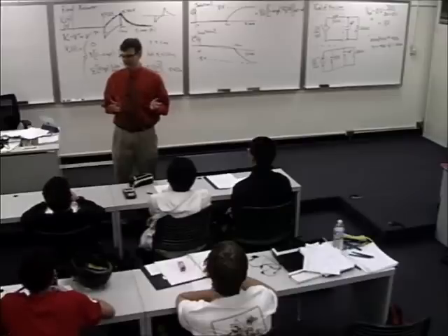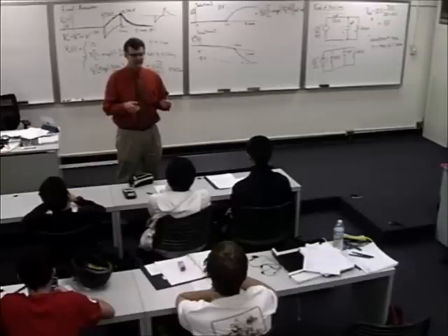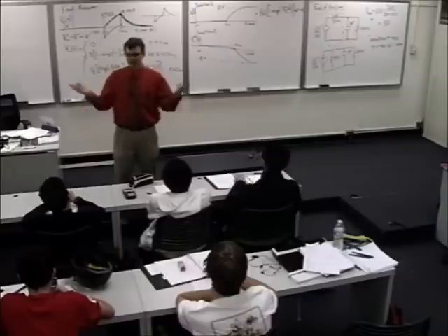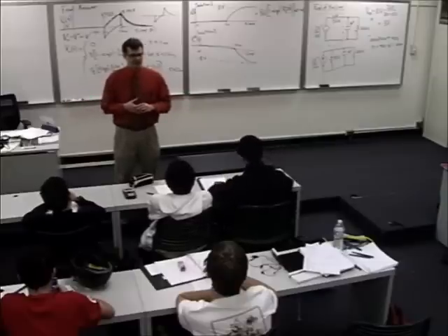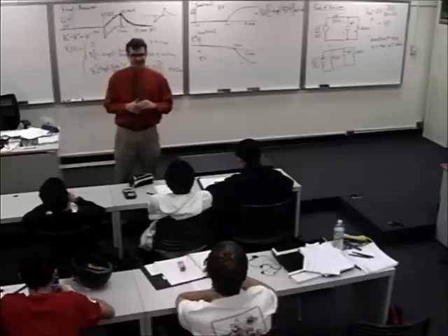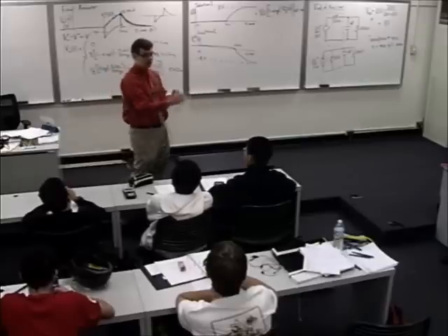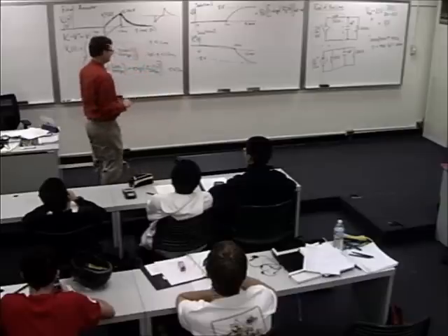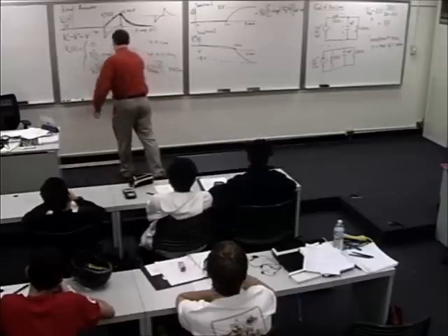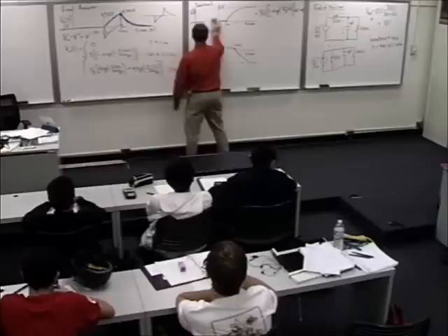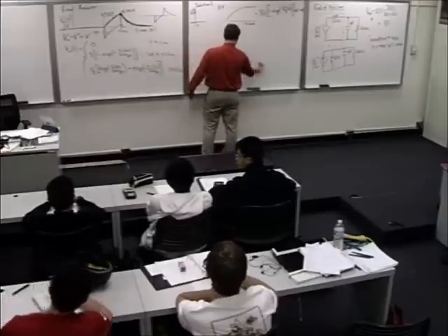And in a way, it makes sense, right? Most of the really interesting stuff in our profession is nonlinear. Transistors are nonlinear. Diodes are nonlinear. Almost everything is actually nonlinear if you put a high enough voltage across it, right? So we want to be able to handle that scenario. If we've got a nonlinear device, like a transistor that could saturate, or a Zener diode, for example, how do we handle that scenario in a transmission line? So that's going to be the start of our next topic. Nonlinear loads on transmission lines.